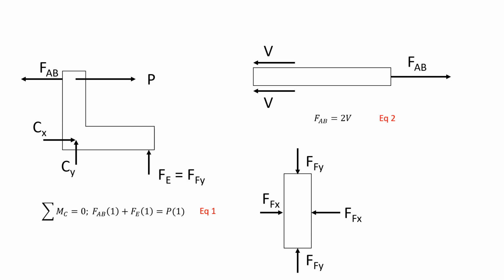Now, we would not be able to make an equilibrium equation by summing forces or summing moment that would relate FFX to FFY, right? But we can relate these two forces by taking note that the total deformation or strain along the x-axis is 0 since the walls are hindering the deformation.